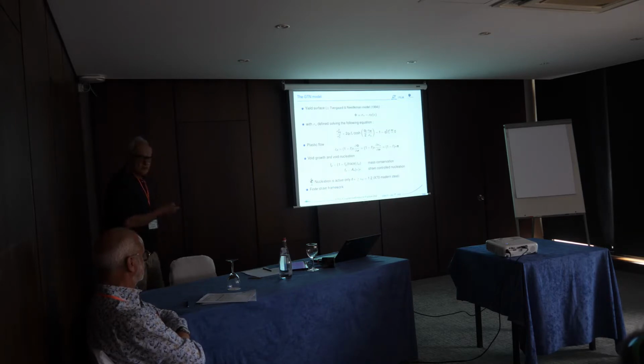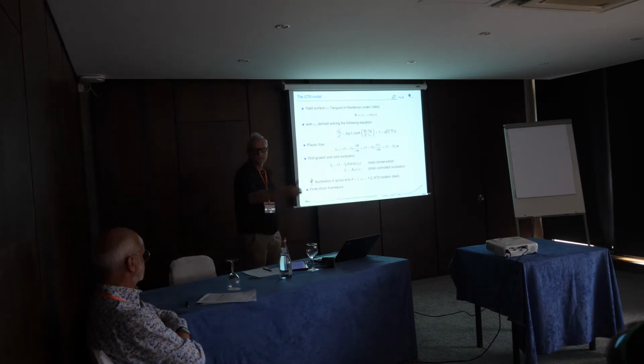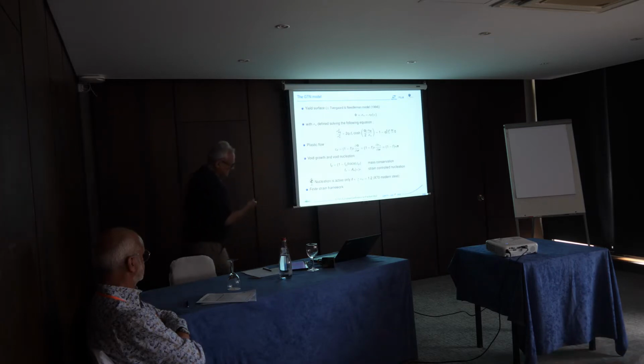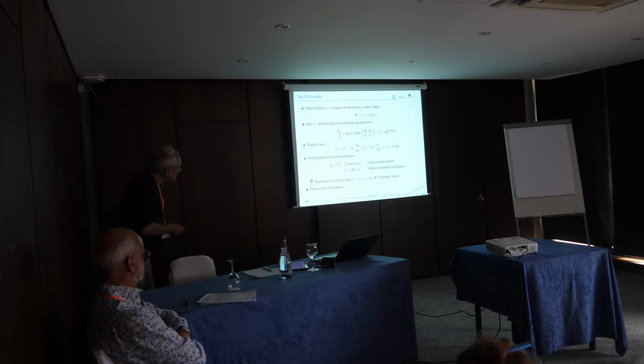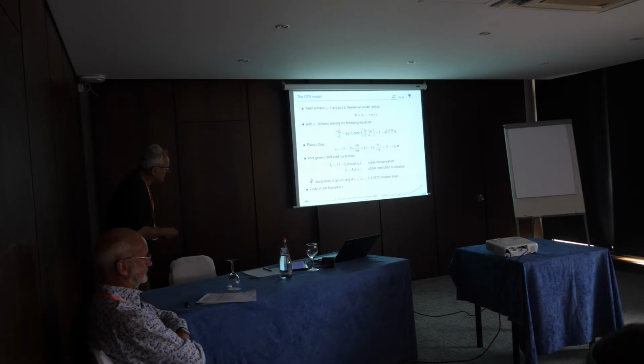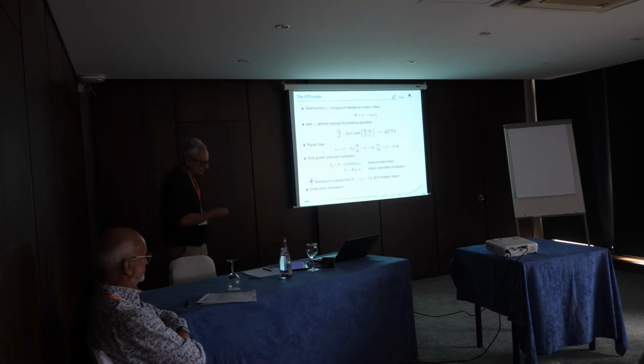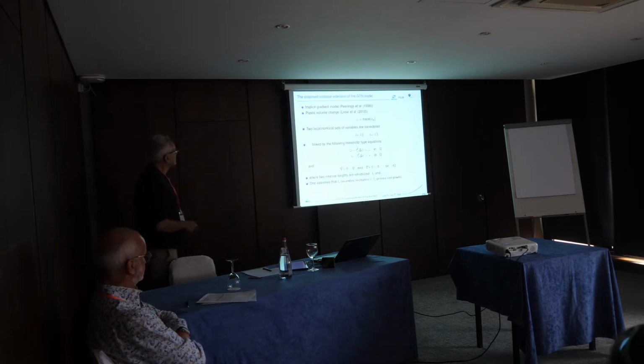Here it is the secondary nucleation on the small particles, so we always assume that you need a lot of plastic deformation before starting this damage process. And here we assume that this is active only when we have a plastic strain higher than 1.2. Remember, it's a model for a very tough material. Indeed, we are using a finite strain framework, which I'm not going to detail here, but it's very important.